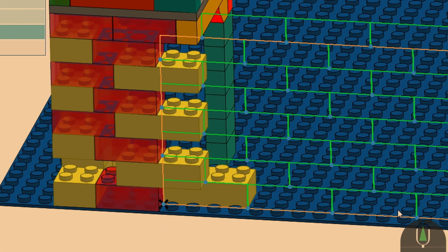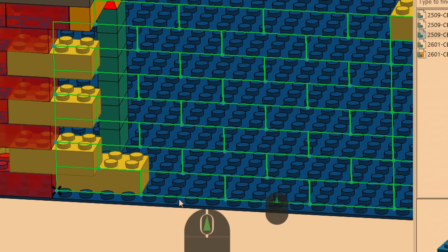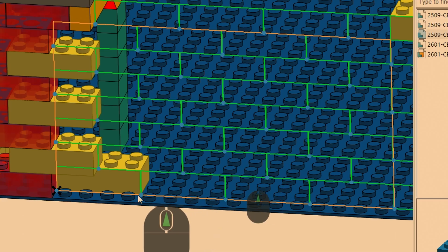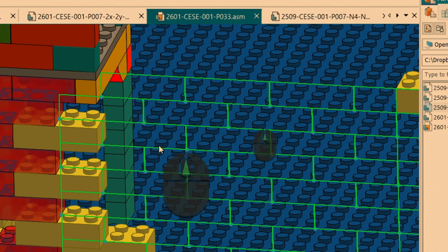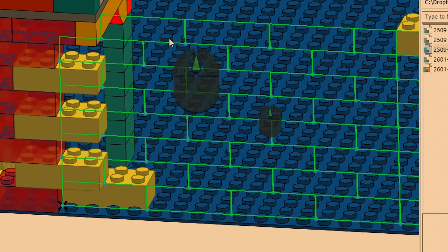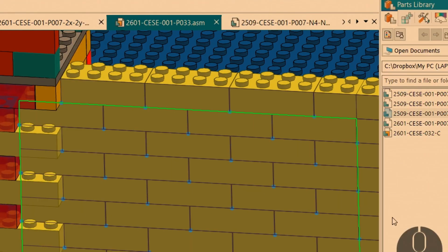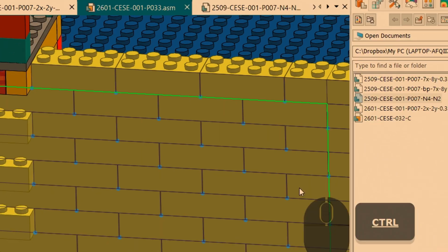So now that we've selected our pattern, it's kind of easier to select because Solid Edge knows where it's looking for the pattern, and there's only really one pattern within the sketch. So as I hover over the outline here, you can see the orange rectangle getting highlighted, and that's the orange rectangle that defines this pattern, this sketch pattern. So I can click on that and Solid Edge builds a wall based on that pattern.